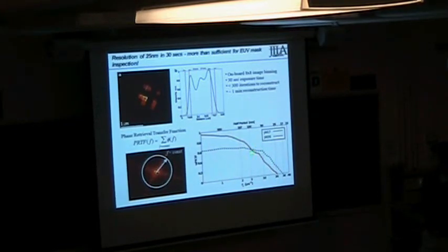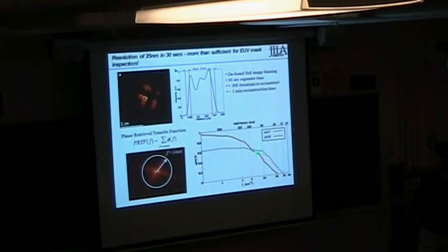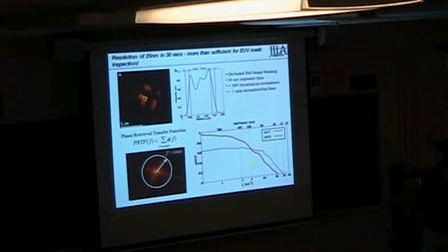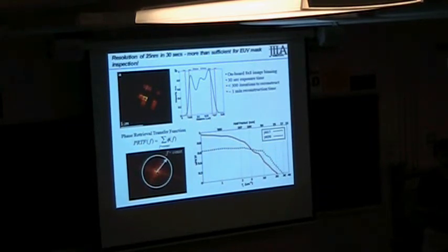And then if you look at these curves, there's also something else to note, where there's a knee in the curve, and we interpret that to be basically the minimum feature size of the sample that we're imaging. If there's nothing in the sample that has smaller features than that, you're not going to get as much of a signal. And so this 100 to 200 nanometer knee is consistent with the size of these slots. And then on the other pattern, we actually have 50 nanometer slots, and that's where the knee occurs here.